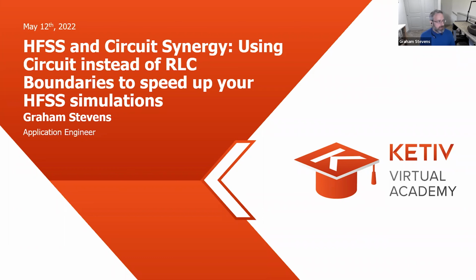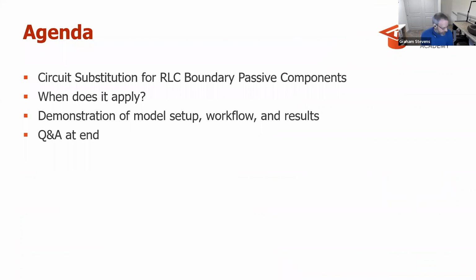I am here presenting a presentation on HFSS and circuit synergy: using circuit instead of RLC boundaries to speed up your HFSS simulations. For this morning, we'll be going over this method of using circuit substitution for RLC boundaries for passive components, discussing when it applies in terms of what simulations, and then doing a demo of how to set this up, the workflow and results, and finally Q&A at the end.